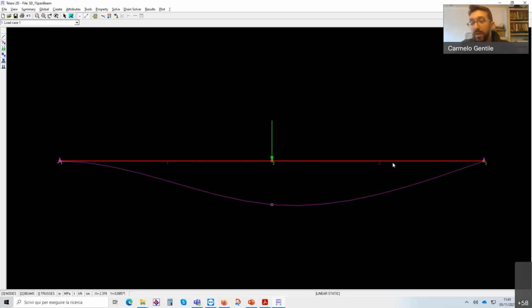And then because the beam is very stiff in its longitudinal direction. This is also an assumption that we make, that elements are always stiff, meaning infinitely stiff in their longitudinal direction. So we can expect some deformation, but it is very small, and we should not be able to see it from this kind of analysis.